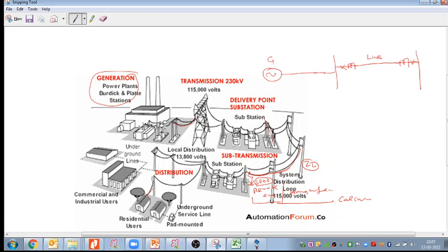Now we are calculating the fault, doing the CT sizing for this one. Suppose first we take the fault happening near the substation, and second we take the fault happening at this location, which we call the remote fault, or through fault. So if we take the overall entire network, what is the source of fault current?